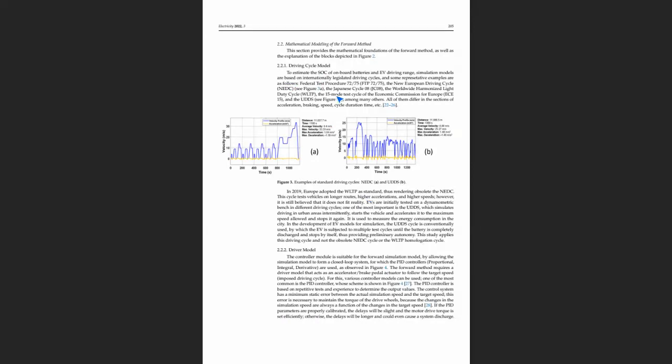In an electric drive system, we need a speed reference. For example, if it is an electric vehicle, you will use one like this. This is NEDC. In your midterm project, you can use NEDC. NEDC means New European Drive Cycle. Vehicle companies, for example Volkswagen, use this velocity curve in their vehicle test procedure. This is a typical city traffic speed curve.